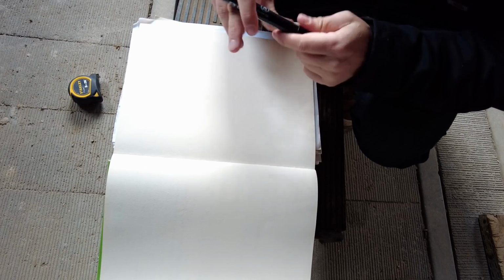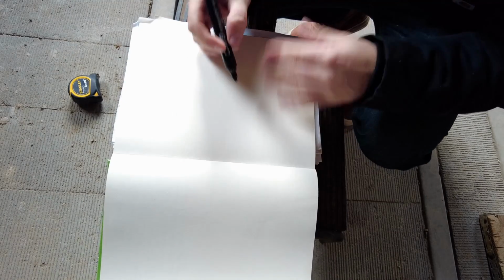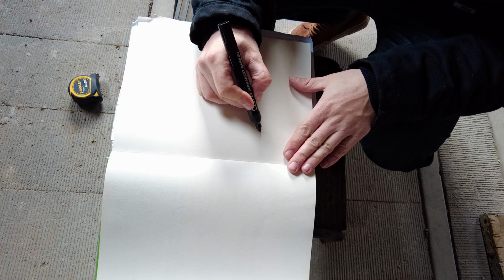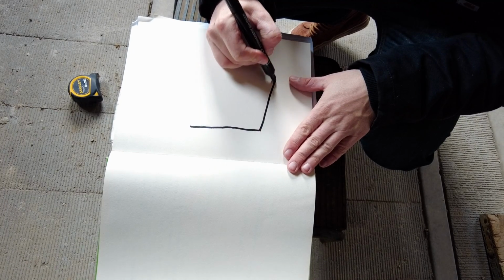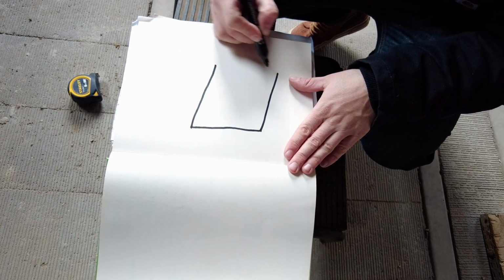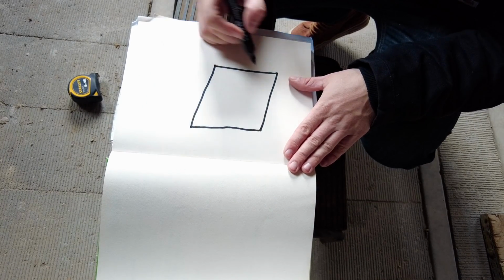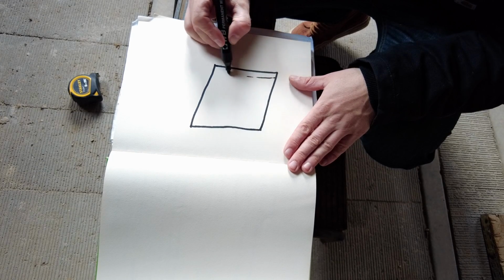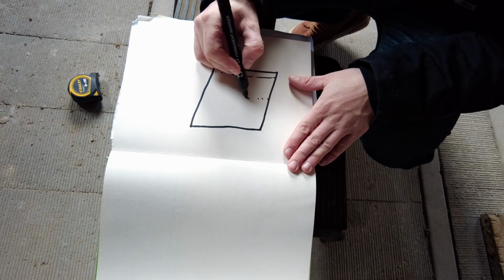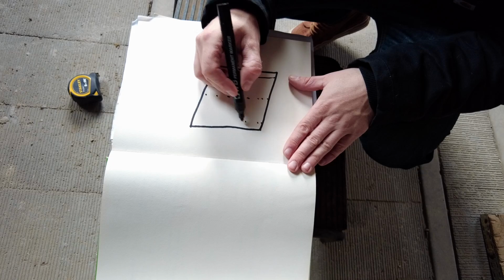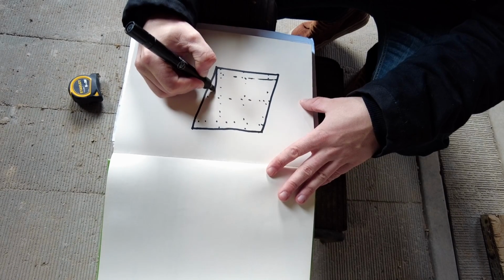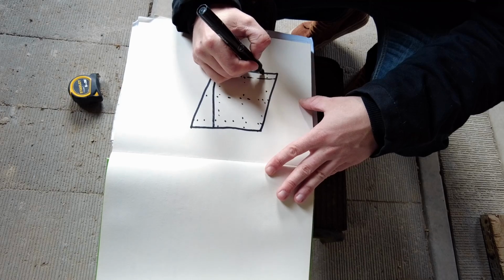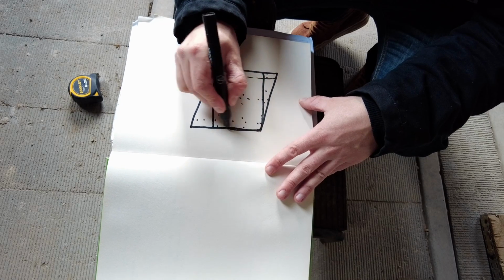There is something else you need to consider. It's whether your window is square, because that will throw your measurements off. Let's show you an example to the extreme. If your window ended up being this shape, if you took your measurements, you would have that one all the way across, that one all the way across, that one all the way across. You could only ever fit a window in that looks like that.